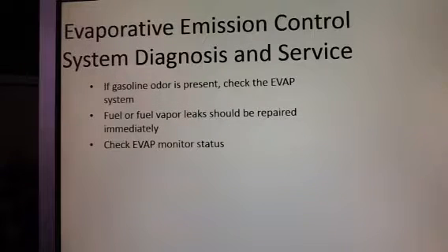Our evaporative emission control system diagnosis and service, what we talked about. If gasoline odor is present, check the EVAP system. It's one of the quickest things we can do. Fuel or fuel vapor leaks should be repaired immediately. We do know that they're flammable, and on top of that, it is an emissions concern that we must take care of.